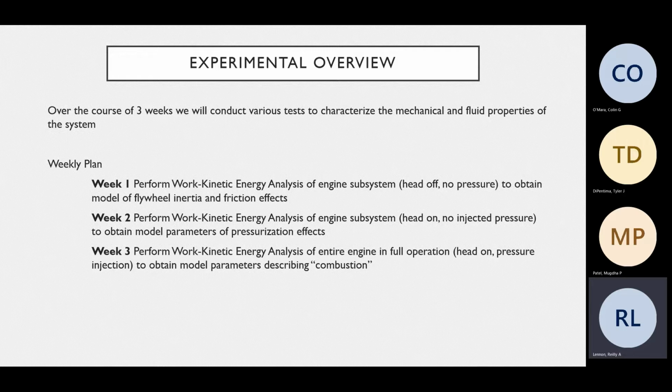On week 2, we're going to perform another energy analysis with this subsystem, though with the head on, without any injected pressure. This means there's going to be air within the system. We're not going to be adding any more, but that air will have some pressure effects. So from there, we can obtain model parameters of those pressurization effects.